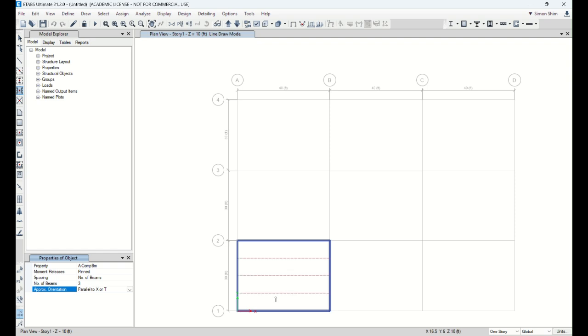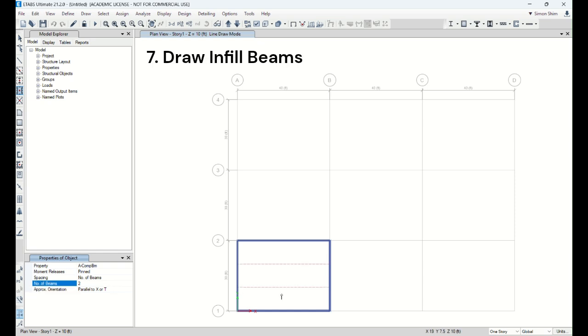I'm gonna add the 3 beams. If you hover, because we have a grid system, right? If I type 2, yeah, it shows the 2 dashed line. It's cool. I think you're gonna love it. With practice, you can build a nice 3D model graphically, amazingly fast. So I click 2. All right. But this is again a moment release pin because this secondary beam is simply supported.